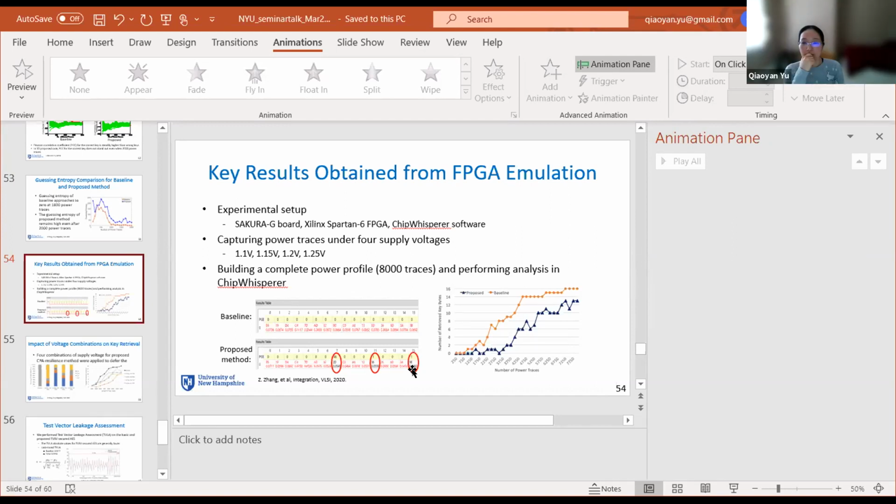I would think the TSV one, because, oh no, wait, I take it back, the interposer one. In general, my feeling is if the fabrication steps, especially on the vertical connection side, make it easy for foundries to access your designs, then that leads to more risk.